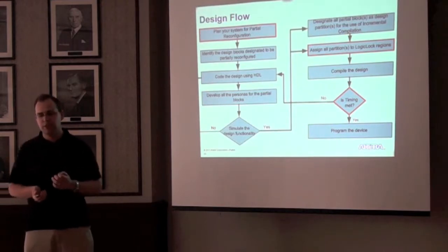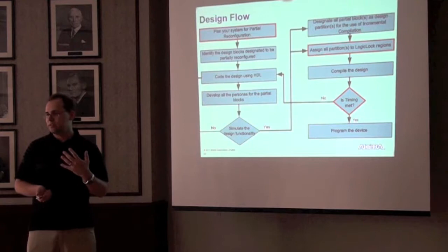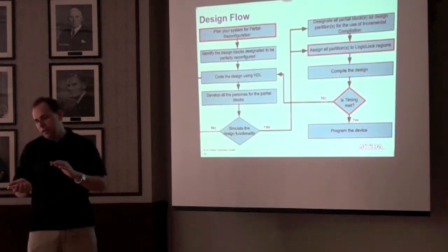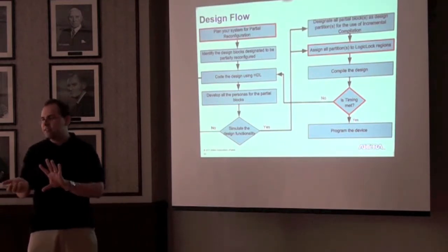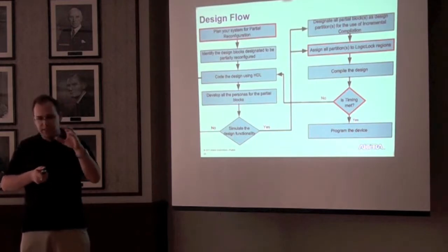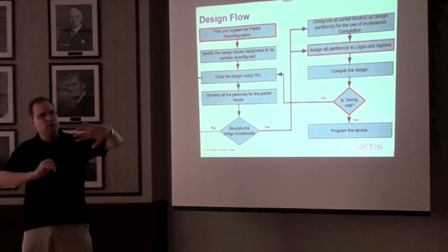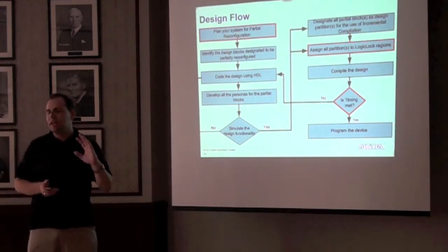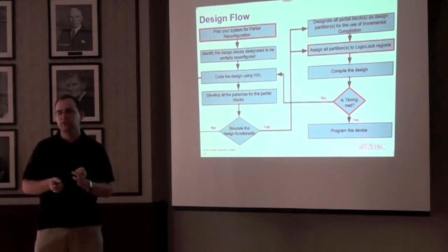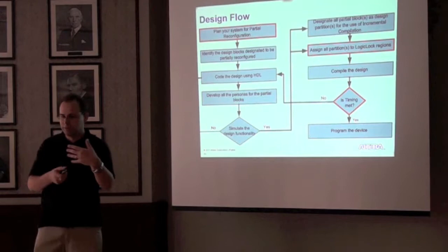so those are just non-rectangular regions in the chip. We do provide a way of doing this automatically. We have something to automatically determine what's a good region size. However, depending on the amount of connectivity, one may want to really think about what those regions are. So you might want to have a finger shape if there's a lot of connectivity between the PR regions, and our automated way of doing that will not take into account advanced requirements such as connectivity. So it's something to think about up front.